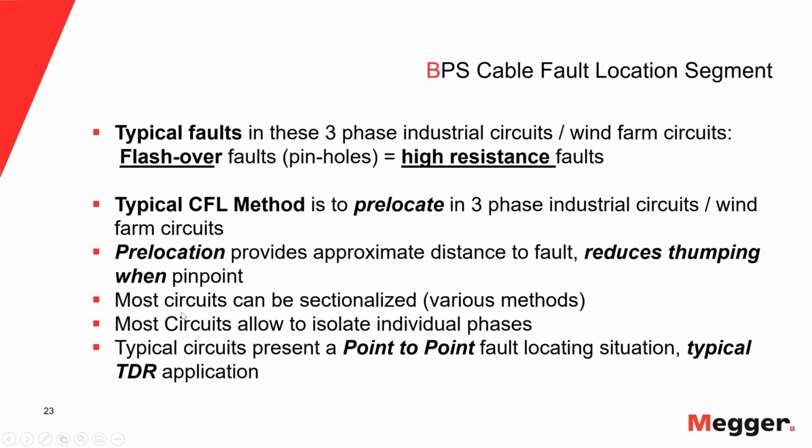So most circuits can be sectionalized by various methods. Many of these circuits have fault indicators installed, so we already have a pretty good idea where to look. But we can also, and I think Marshall eventually will talk about a sectionalizing method in URD loops, that same technique could also be used in some of these circuits.